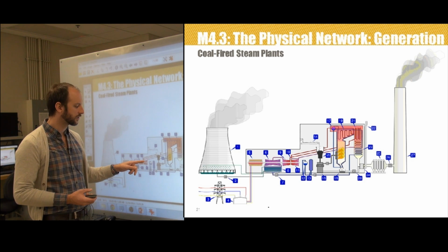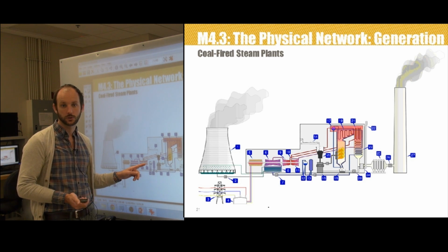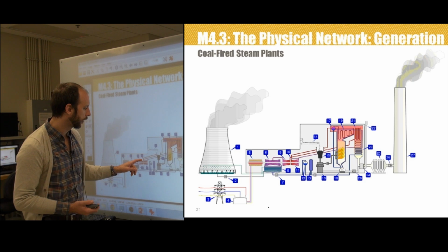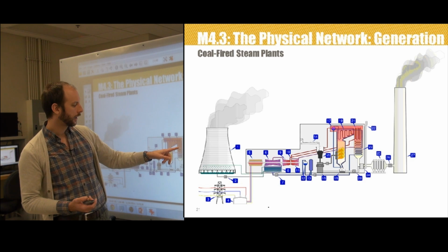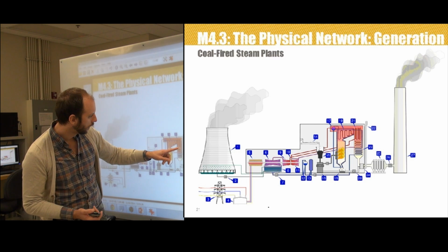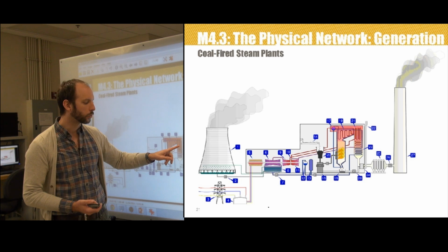The steam is then exhausted from the high pressure turbine, and it has been reduced at this point in both pressure and temperature. And so then what happens a lot of times is it's flowed back to a secondary system in the boiler called the boiler reheater, 21 here. So it's just a heat exchanger path that reheats the steam.